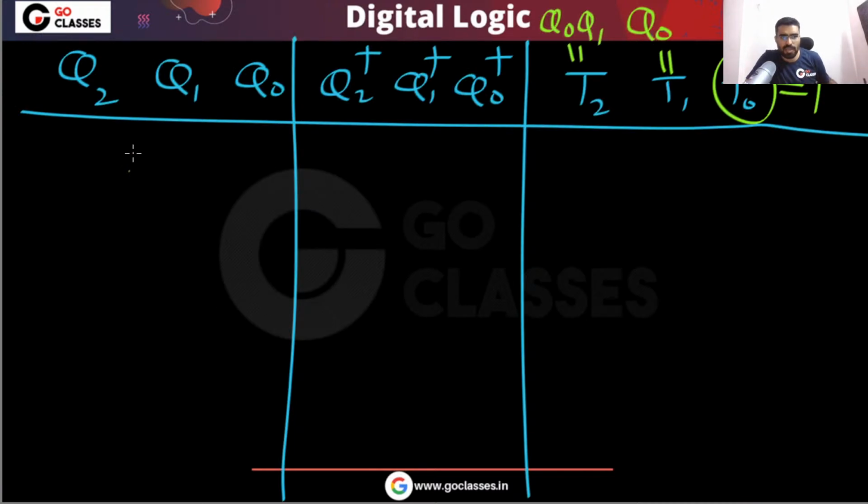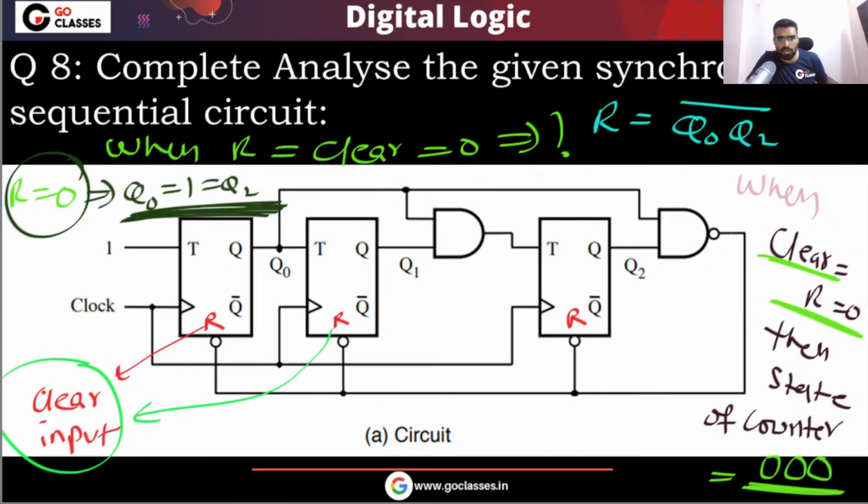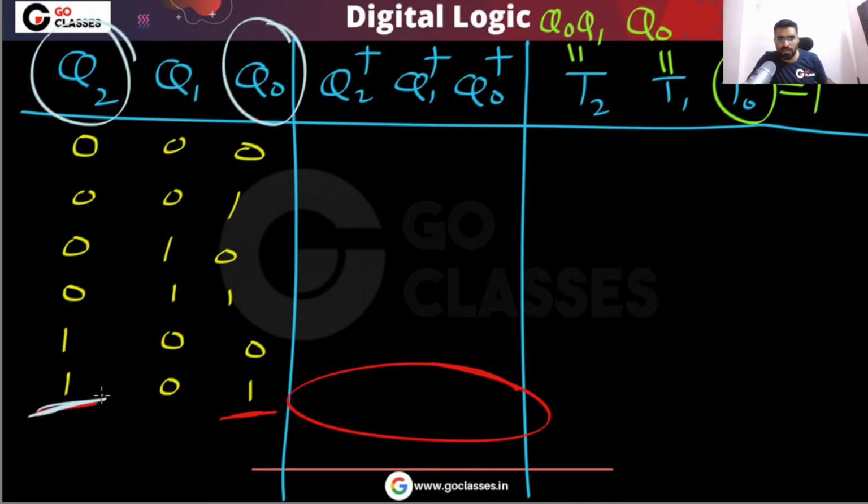So let's see this. The table will be like this: 0, 0, 0, 0, 0, 1, 0, 1, 0, 0, 1, 1, 1, 0, 0, 1, 0, 1. Now you tell me, when Q2 and Q0 are both 1, what should be the next state? When they both are 1, then the next state will be 0, 0, 0. Correct?